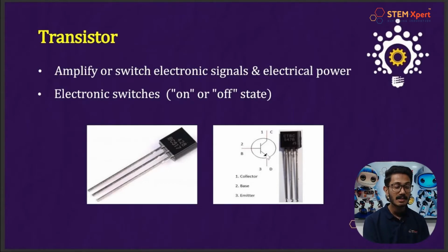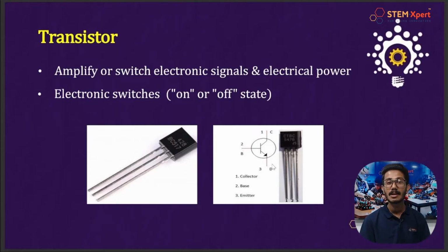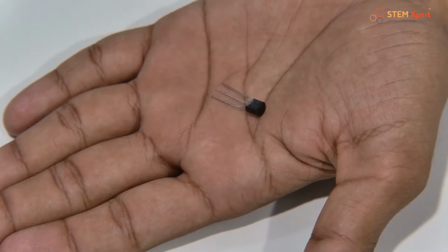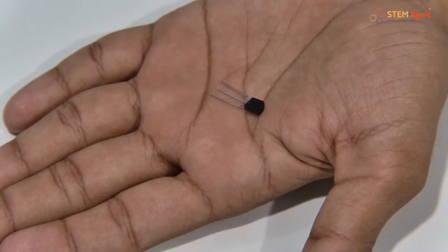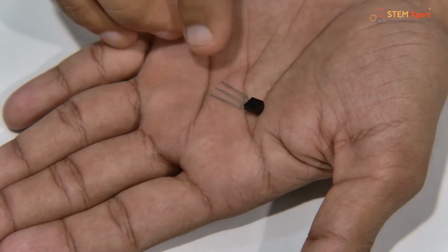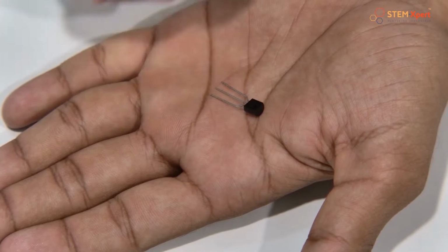Here, as you can see, this is a symbolic representation of our transistor, because while we are creating our project, we are following a particular circuit diagram of automatic street light. In this session, we are using the BC547 NPN transistor. So remember, a transistor is basically used to act as a switch. It has three terminals: collector, base, emitter respectively.